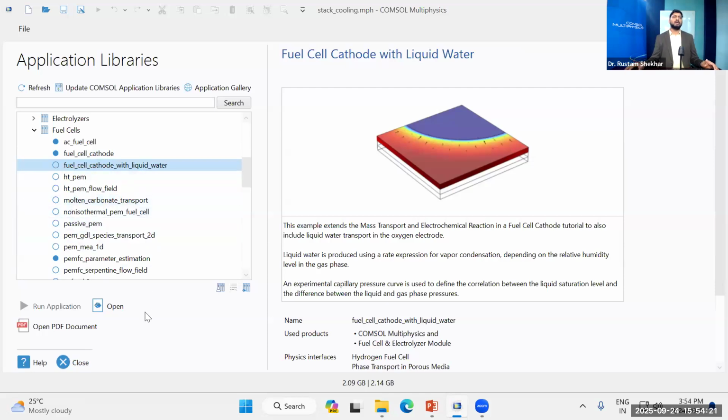And one example I showed you in the presentation where we are directly giving the water in steam form. Water in steam form is generally given to the electrolyzer where they are working at high temperature, more than 100 degrees Celsius. So it is just an inlet condition which you can provide and you can work with. So that is feasible. Going high temperature, generally I can see it's a bit simpler than the lower temperature. The only thing is that now we will be facing the challenge from the material property side.